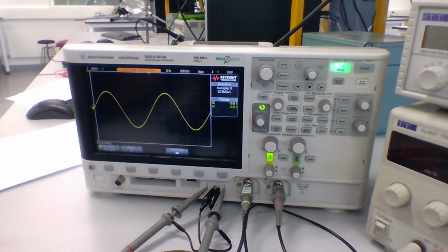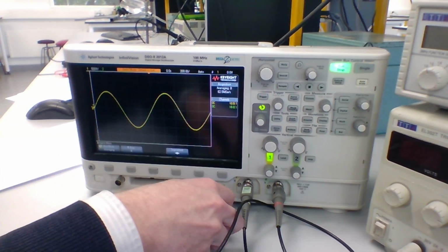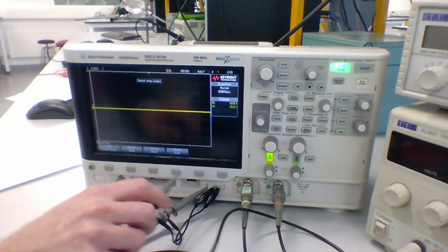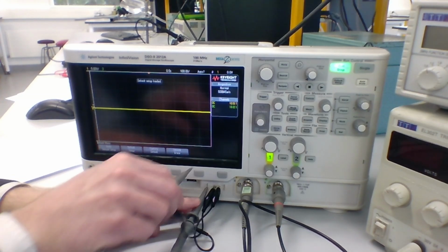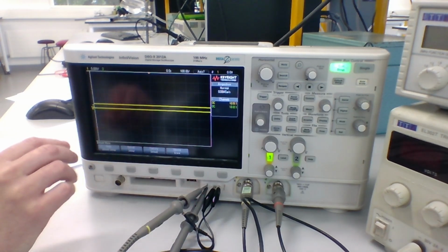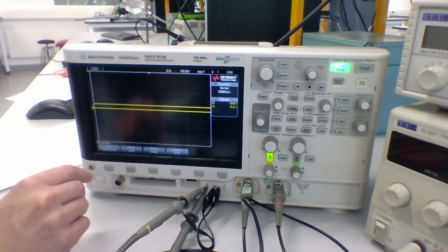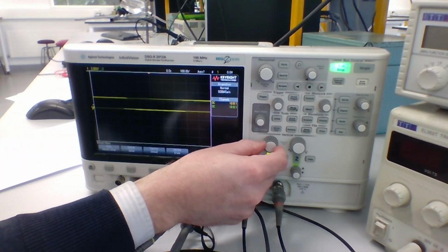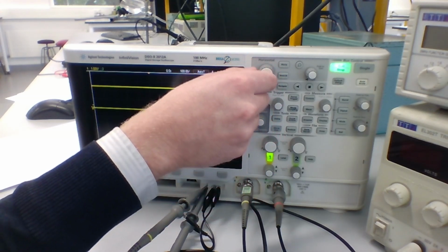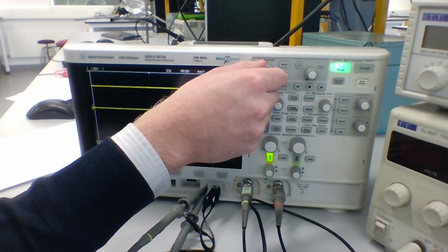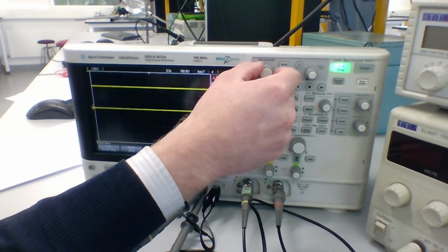Once you've had a read through of that section, following the instructions, we're going to connect both oscilloscope probes. I'm going to reset the oscilloscope and connect both probes to what's labeled probe comp or demo 2, which is the hook on the left-hand side here. We're then going to change the scaling on channel 1 to 1 volt per division. And we're going to change the time base as well to 200 microseconds per division.